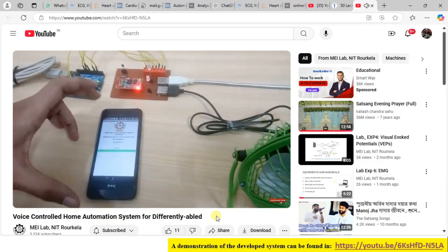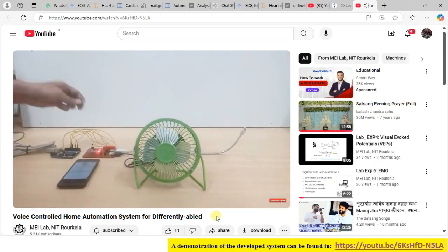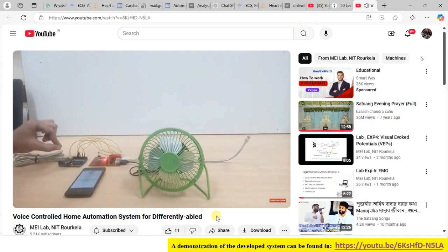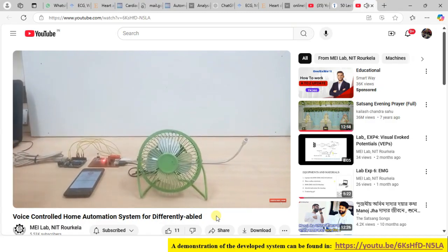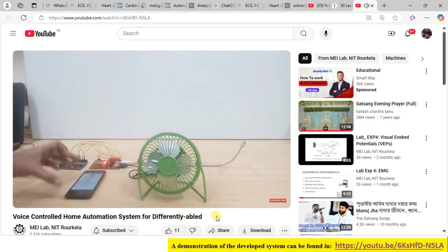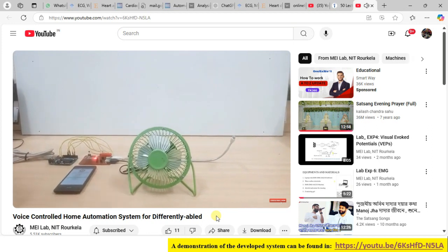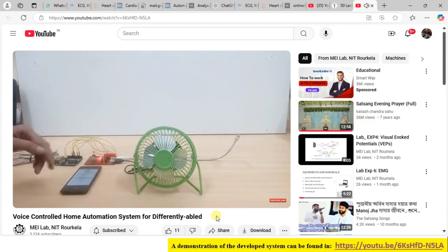On receiving the signal, the Arduino board issues a command which goes to the Android app via the HC-05 Bluetooth module. On receiving this command, the Android app launches the speech recognizer, and now the subject can speak his command into the app. This command is then converted into text, and this text is again sent back to the Arduino program via the HC-05 module. Here the Arduino program ascertains what command has been received and then takes the corresponding action.